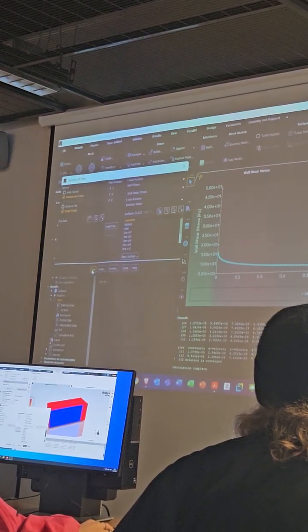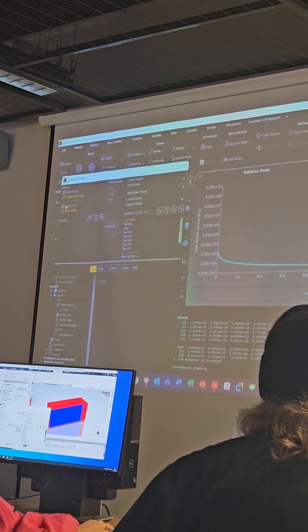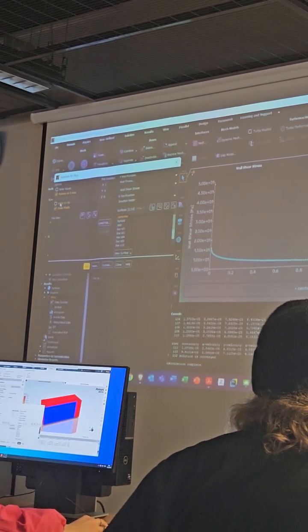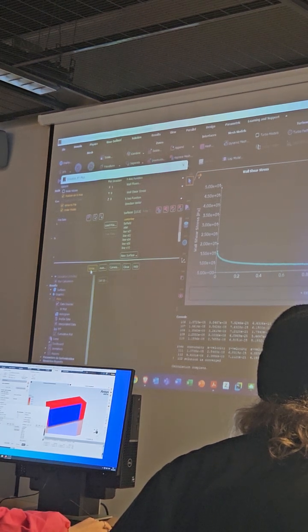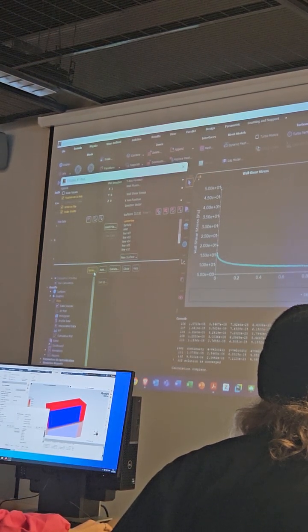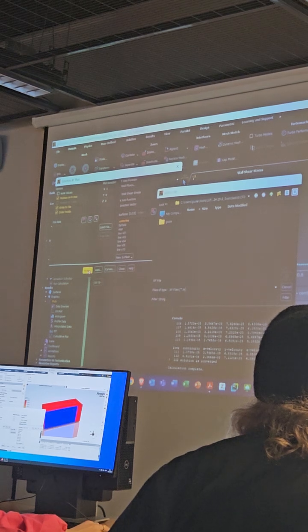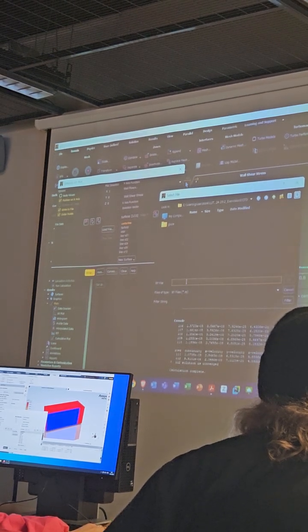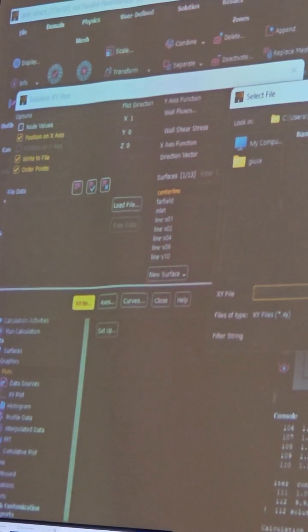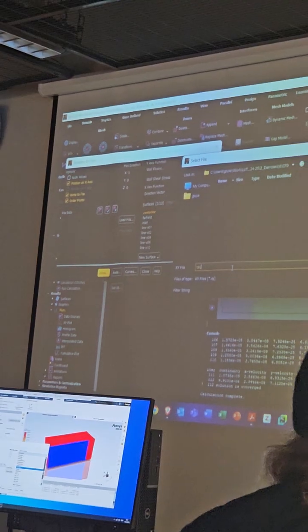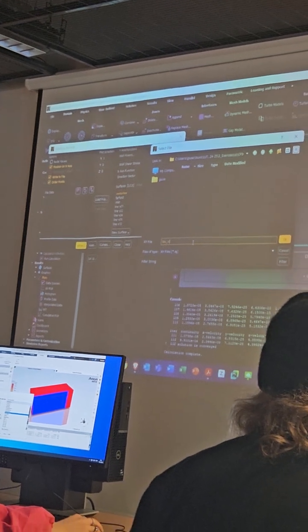And we can save the file now. So we select this Write to file option. Instead of Save Plot, now we have Write. So we hit that, and we have our working folder. We can save a file. I'll call it tau_w.